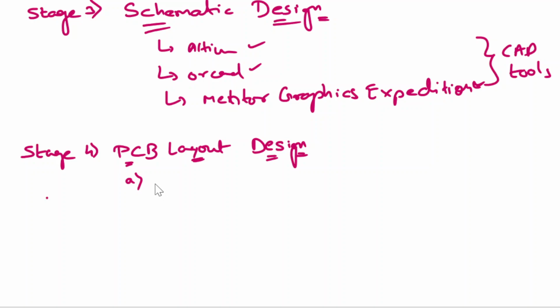That's why you have to find out the right manufacturer who is suitable for your design. If not, then you can change your design according to your approved vendor manufacturer, based on what layout stack-up they can support. So either way you can go for it. Got it? You told about dielectric thickness.